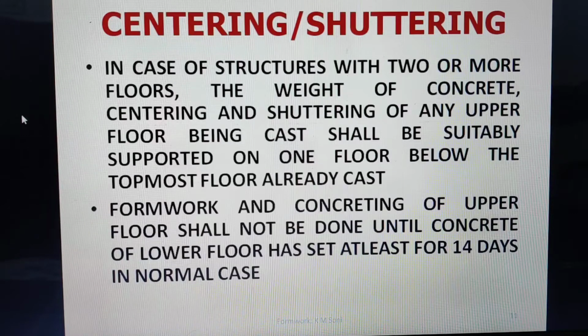So in case of structures with two or more floors, the weight of concrete, centering and shuttering of any upper floor being cast is to be suitably supported on one floor below the topmost floor already cast.